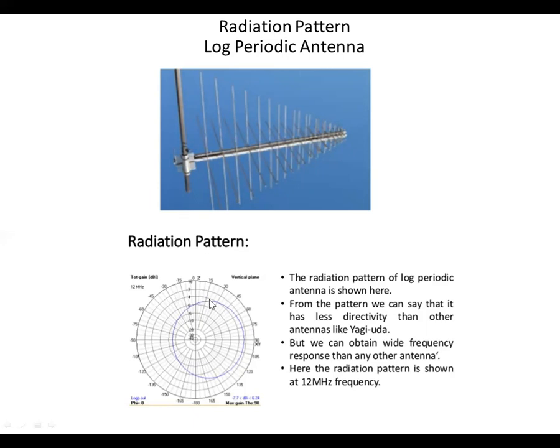But the one downside is it has a fairly omnidirectional radiation pattern, so you really can't focus it. You would think, looking at this pattern here, you could put directionality onto the signal like you do with a Yagi, but it didn't work out that way. I forget what the frequency range is on these.